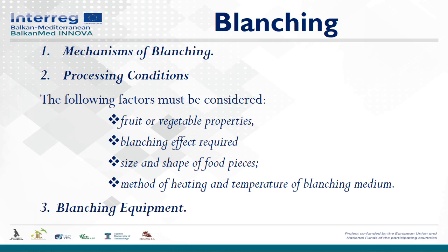The main purpose of blanching is to inactivate enzymes, which through their activity would lead to lower quality of the processed product. Inactivation of enzymes prior to the sterilization process is very important, as severe processing will virtually destroy any activity of the enzyme, but it may take a considerable time before the food can obtain the proper heat and temperature. So, quality can be better maintained if enzymes are destroyed prior to sterilization processes such as canning.